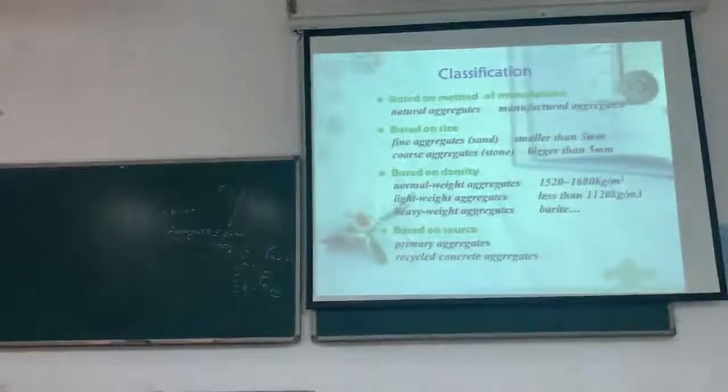Maybe we cannot use all recycled aggregates. Maybe we can just add 30%, 40%, and mix with the fresh aggregates, just like the primary aggregates. Mix them. We cannot use 100%. Please be careful. Well, this is about the classification of the aggregates.